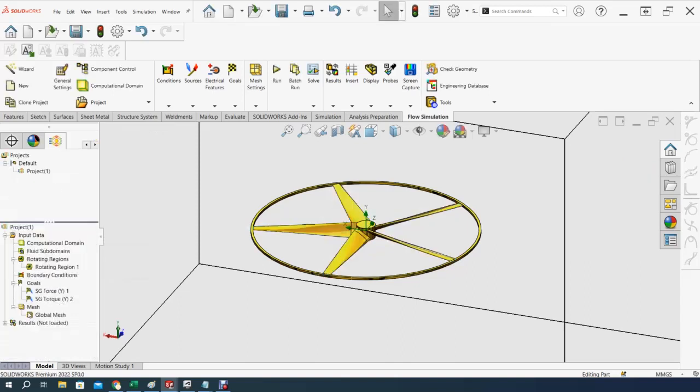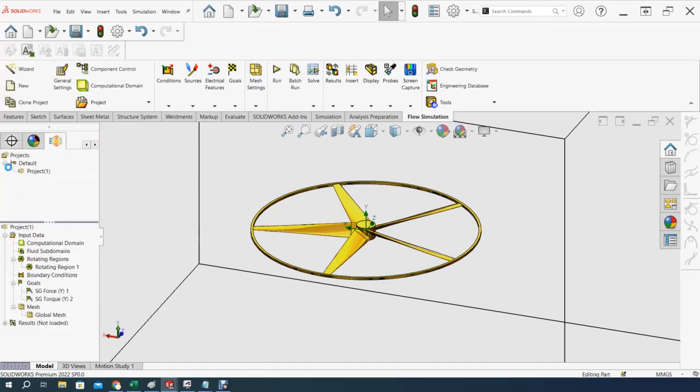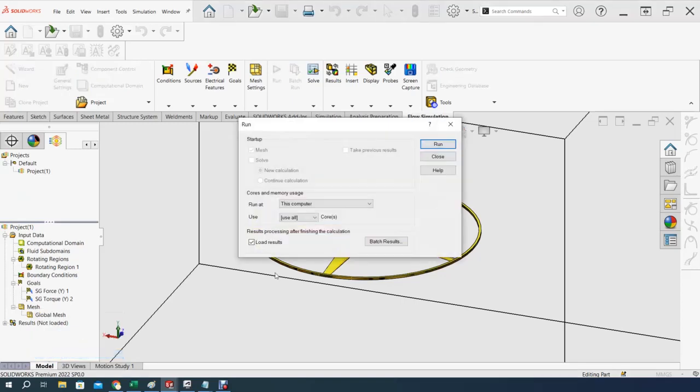Now, how about mesh? Let's see. Let's go edit definition. It's kind of low, 3. I can start with that. The higher this number, the more resources we'll use from the computer. Let's say 4, and let's say OK. And now let's create mesh based on that.